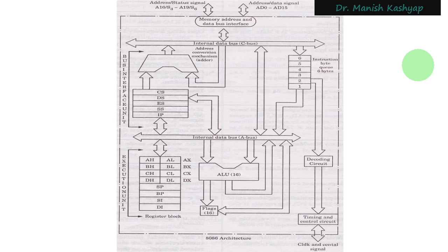At every memory location, you still have an 8-bit storage capacity. So you have 2 raised to the power of 20 locations. Each location has got an 8-bit capacity. This is 1 byte capacity. So now if you see, the address of every location could be of 20 bits. Its address has to be of 20 bits.